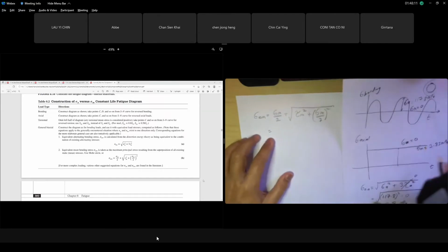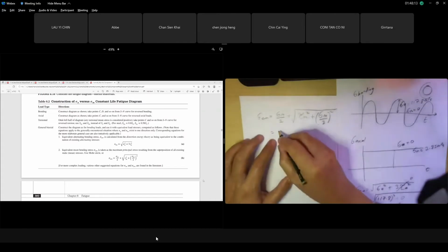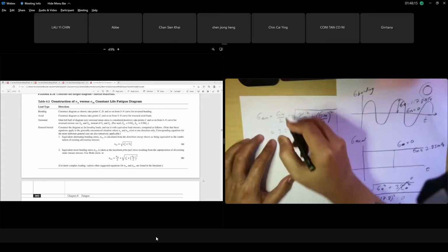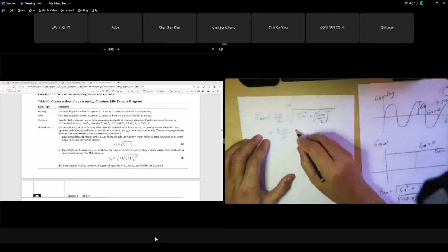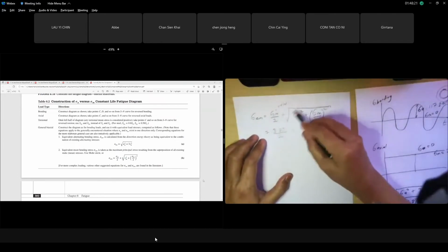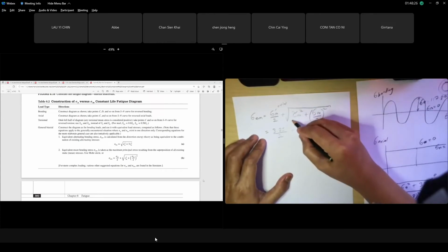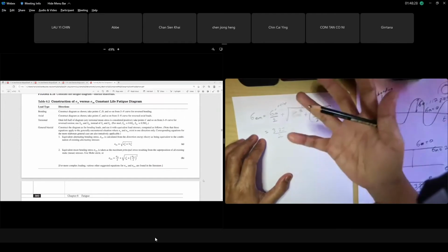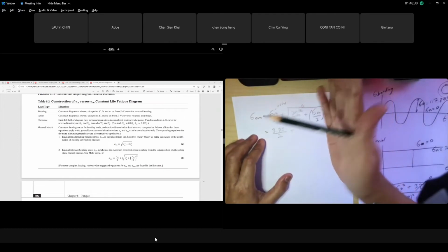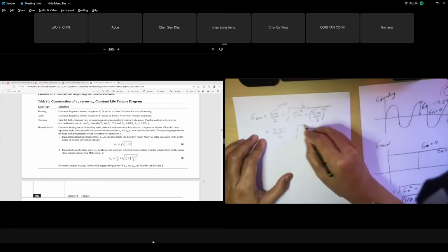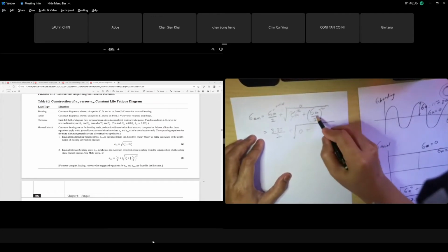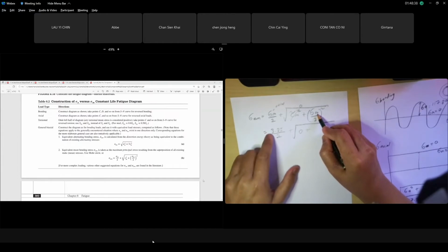Yes, Doctor. Okay, so we use 3.85. So 3.85. Okay, this is axial. Okay, 3.85 over 2 plus. Okay, we don't have tau, right? We don't have any torsional stress. Betul tak class? Class? Zero kan? No tau. We don't have torsional stress at the notch, at the groove. Okay, plus, okay, this one is 0. Okay, we have sigma min tadi adalah axial lah just now kan.